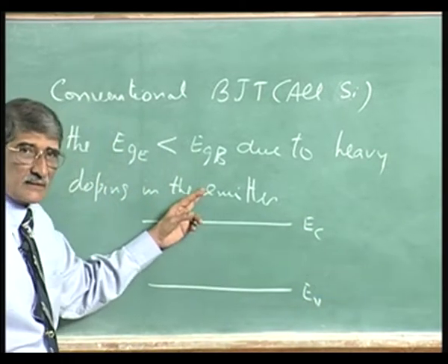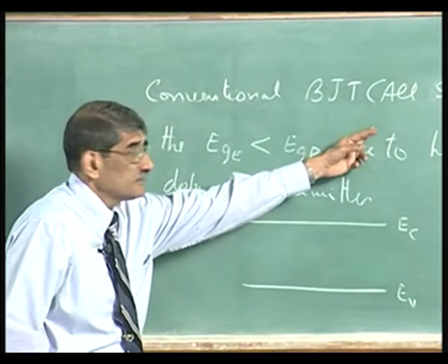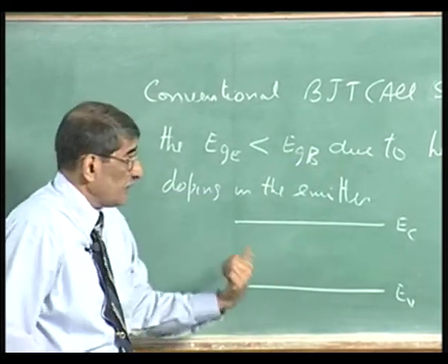This is not a heterojunction, all silicon, still your band gap in the emitter is smaller because of the heavy doping effect.